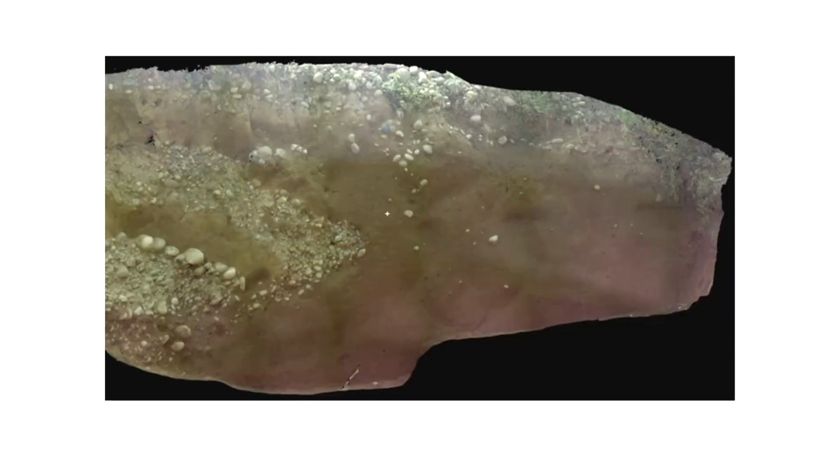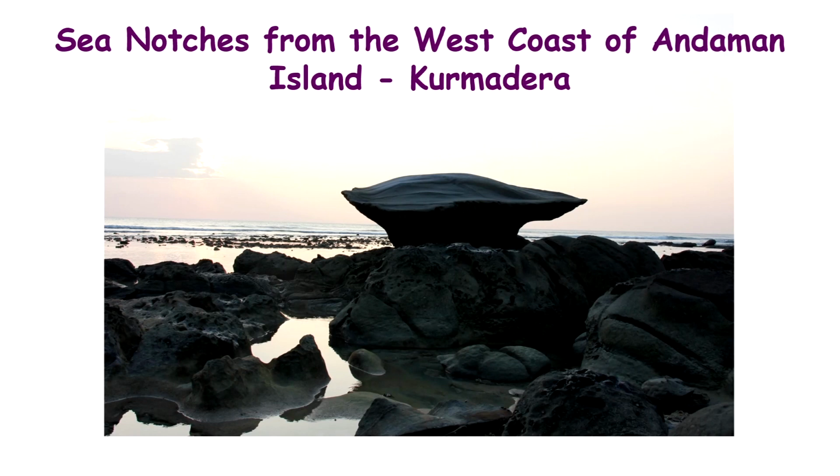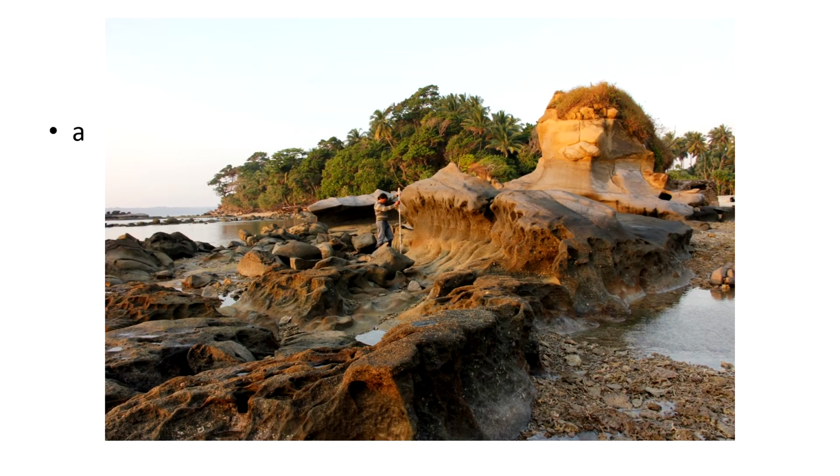Okay. And another advantage of the total station is that one can use it for scanning the outcrops. So this is the scanning which we did for one of the trenches which was opened in Punjab. This is the exposed wall we have photographed and digitized completely, okay. And we can also map, because it has a laser which can continuously keep on measuring or recording the topography in vertical section as well as horizontal.